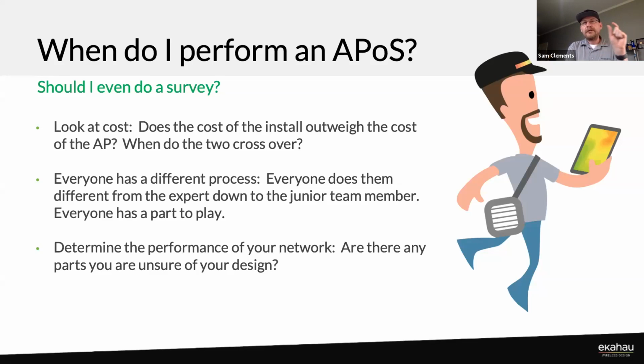And if your application requires you to go out and empirically measure that you're going to get gigabit Wi-Fi or 500 megabits per second throughput or whatever, and you are doing that in a battery-powered scenario where a battery has not provided enough power to turn up all of the radio chains, then you absolutely could be measuring data that is incorrect, and you could be making decisions based on bad data. Yeah, no doubt about it.